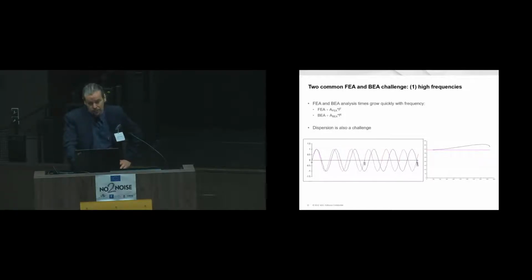You also have a big issue, especially in finite elements, which is dispersion, meaning that your amplitude is well predicted, but the phase is different because the numerical speed of sound is different from the actual speed of sound, and it can lead to errors in eigenfrequency predictions or some issues when you have different techniques where you have to match the waves. So usually for big problems, it's the main source of errors, and it's the biggest constraint on the element size.